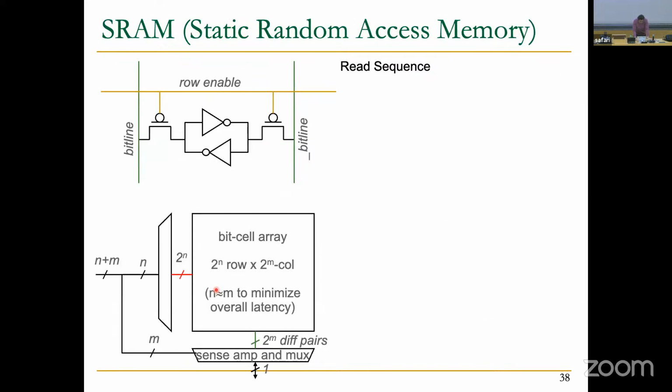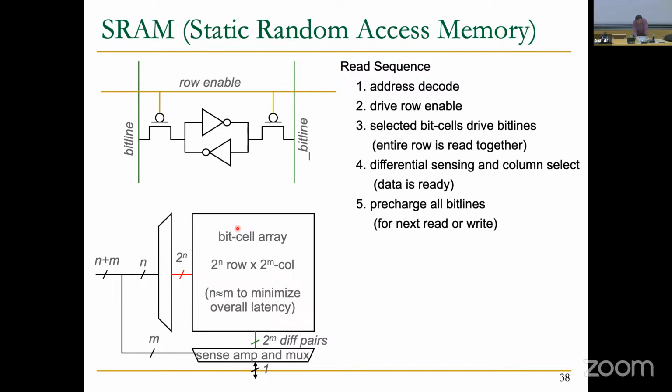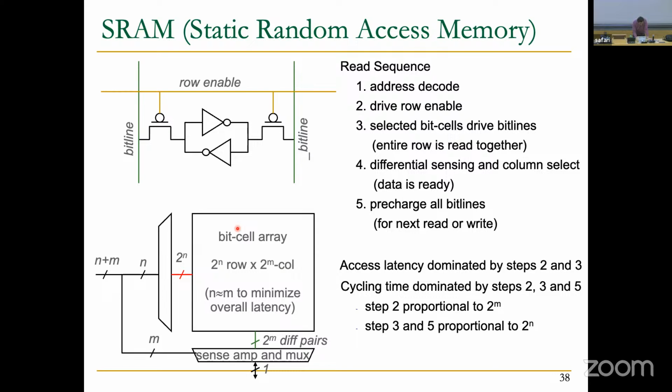And the main difference between an SRAM array and a DRAM array is basically that SRAM resides in processor chips, so you have more opportunity to add wires, and this will provide you with the possibility to provide row and column addresses to your array structure in the same clock cycle, whereas you won't have that in DRAM, and we'll see it in the next slide.